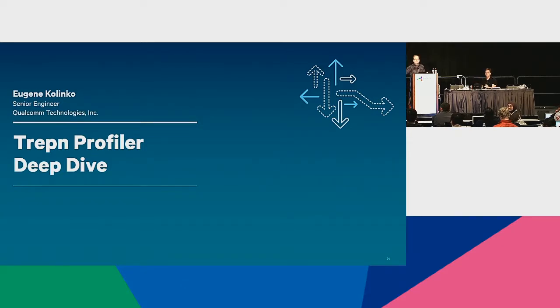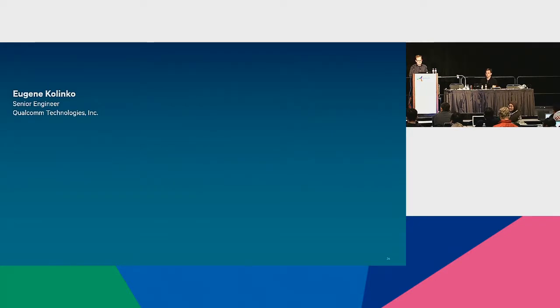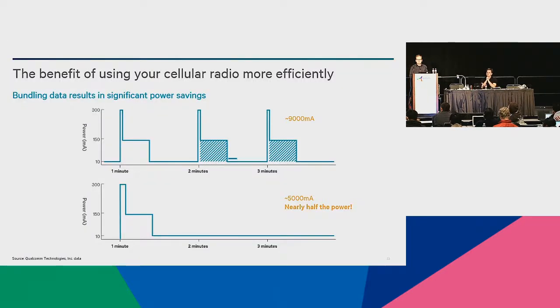What about turning the radio on and off with those gaps you were showing? Is that effective? Because the radio also takes time to turn on and turn off, right? It does, although it's pretty efficient. There is a ramp up, you're right, but it's not really a problem. The processors do a very good job of doing that. But you do have the ability to close a connection versus just letting the connection time out. And simple things like that can save a ton of power.